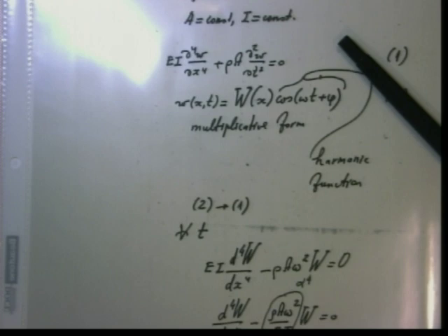Now, if this is so, if indeed this is a solution, then it is a magnificent solution because look, for 1 degree of freedom system, I did not have W of x. I just had cosine omega t plus phi. Here, the only complication is that the function of time is multiplied by a function of axial coordinate. But otherwise, the whole thing stays as it was before. Nothing has changed, so to say. This product was also suggested by Bernoulli and Euler in the same year when they suggested it. So let us substitute this equation 2 into equation 1.